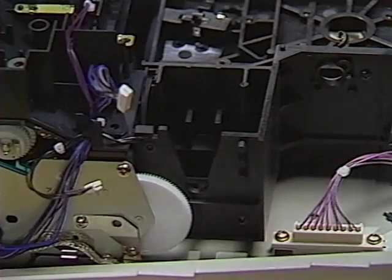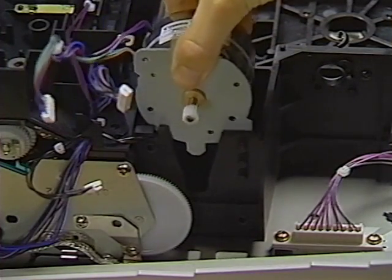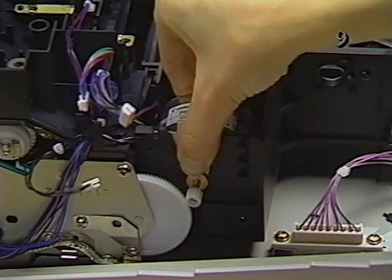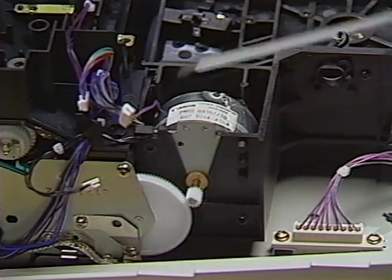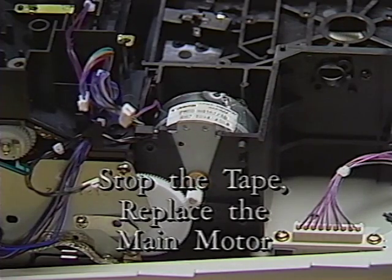Replace the main motor. Start by lowering the main motor into its chamber on the printer chassis. Then replace the 2 main motor screws. Stop the tape and replace the main motor.